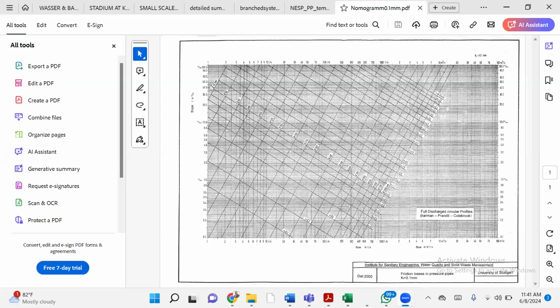Nobody's doing that one anyway. You cannot go more than 120 meters without having a manhole in a network. So these are standard rules of thumb. And last week I told you, if you are doing infrastructure design, I have seen many people using 50 mm, which is what you are saying now.